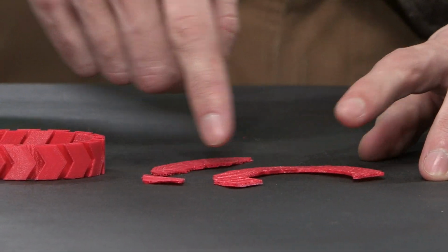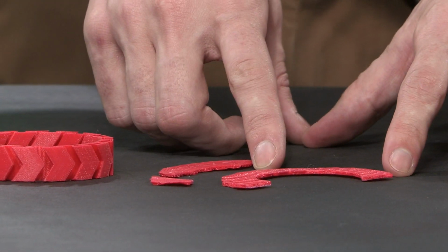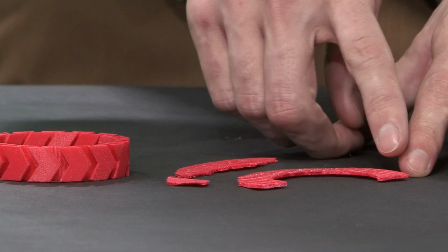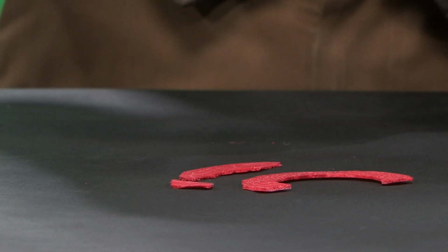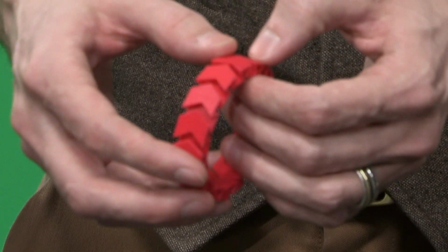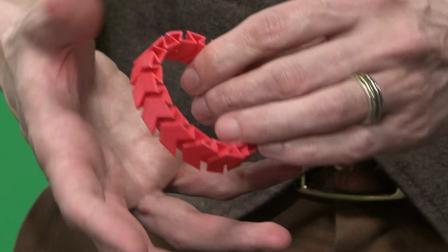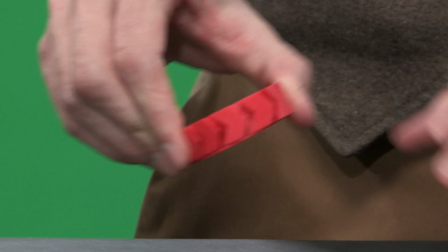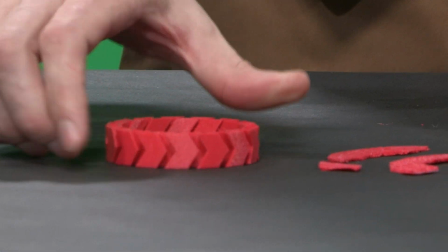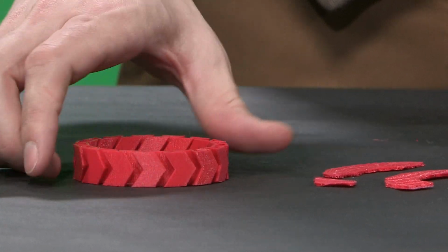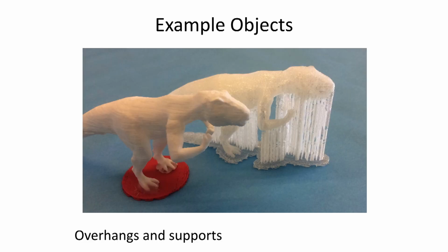And the raft begins with some high surface area threads basically placed down, these layers, these broad threads right there. Whereas then the high resolution layers can occur inside the shape itself. And of course, this is also a great example of a shape that's flexible because of its geometry, not because of its material. It's also important for us to be able to minimize errors by producing those supports.